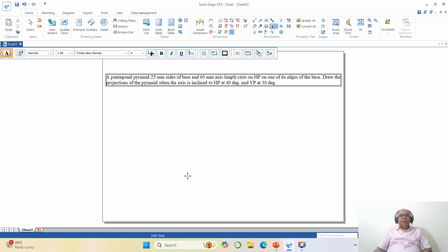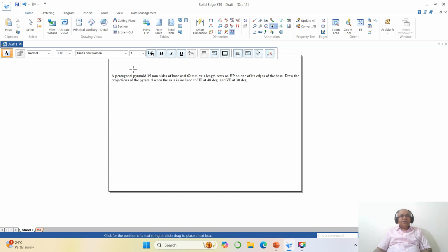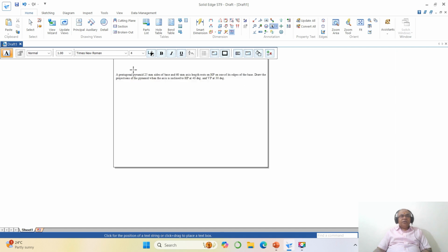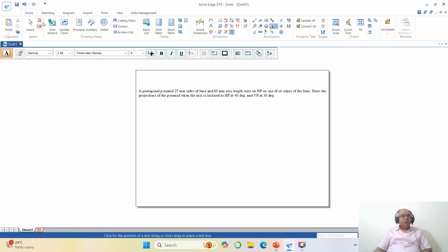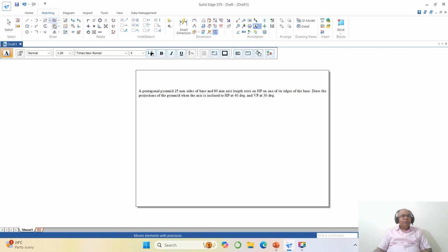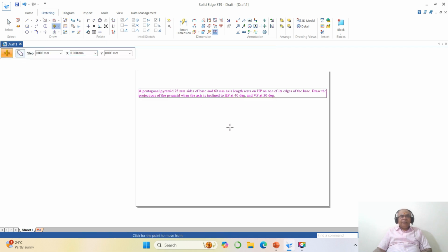Full stop. Now right click on the mouse button, take the drawing sheet nearer to this, go to Sketching, come down to More, disable Copy, select this, and keep the text wherever you want.